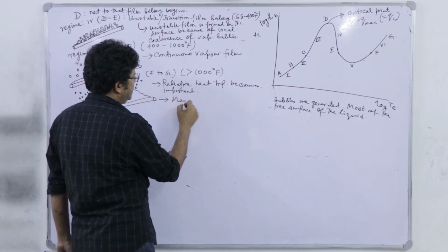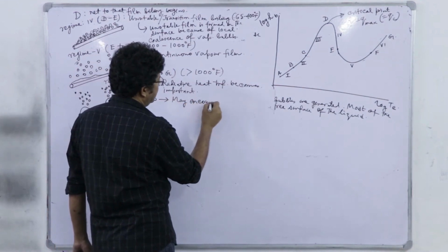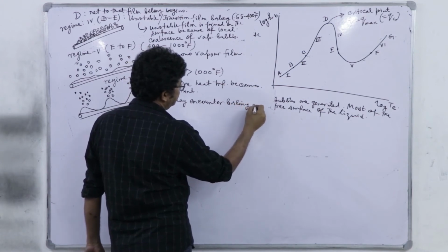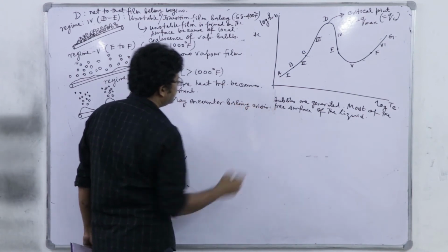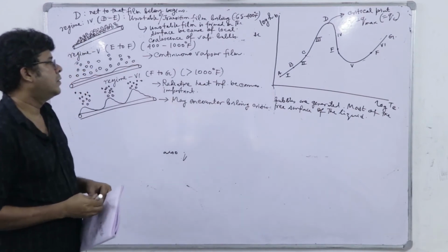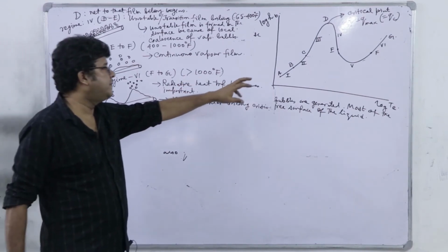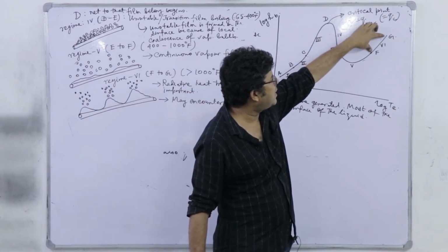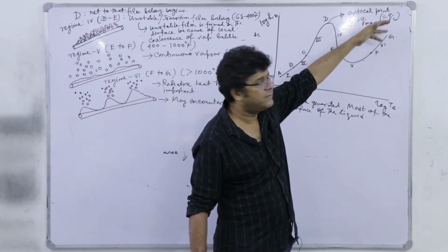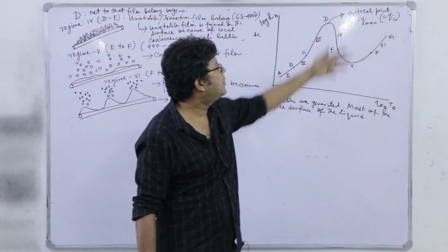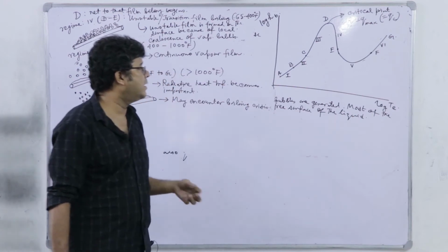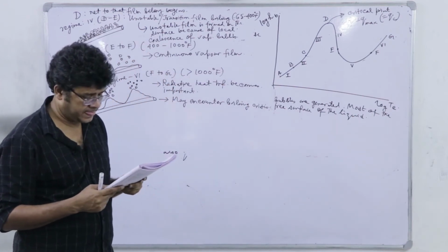We may encounter boiling crisis. Okay. So, the most important feature of this regime is that radiative heat flux becomes important, and this curve we have to terminate because we can't go beyond, as there may be melting or burnout of this heating coil.